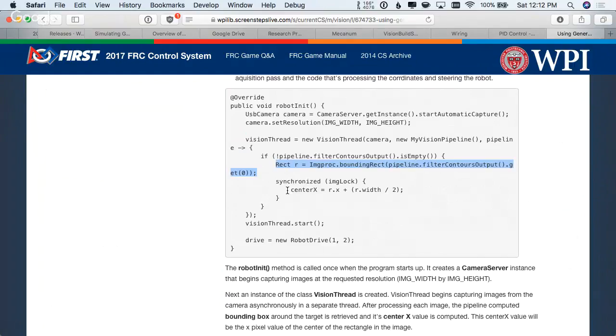This runs on your local machine, right? This runs on the RoboRIO. This example is everything on the RoboRIO. Yeah, you plug the camera into the RoboRIO, you take these classes and stick them into your robot program on the RoboRIO, and then it does it there. If you want, the output gets sent directly. It's right here. Here's the center X of the goal. So if all you're doing is aiming, right?